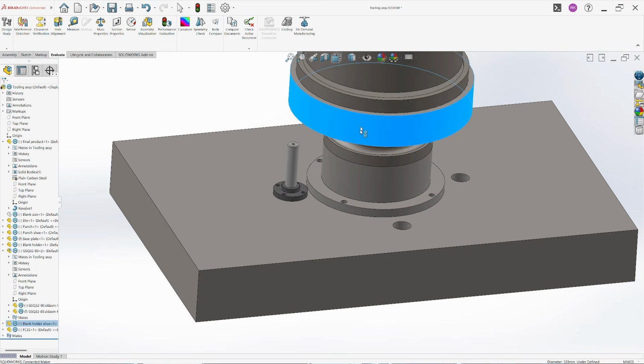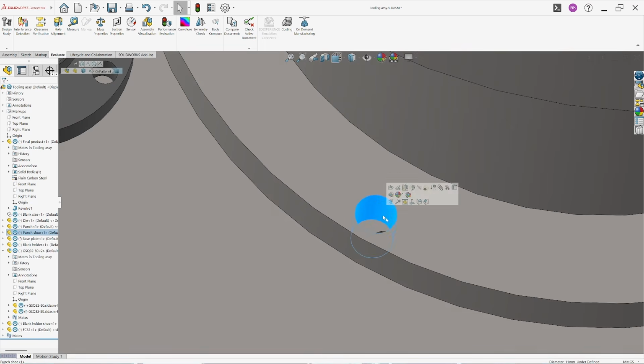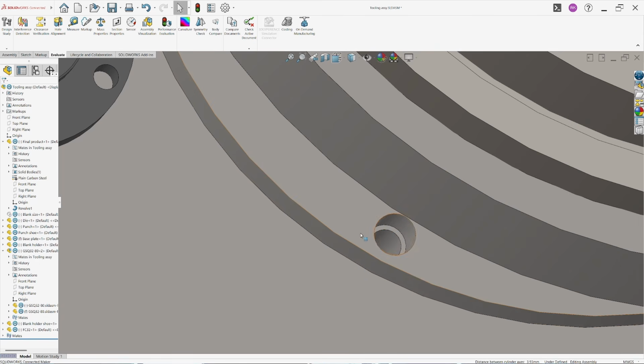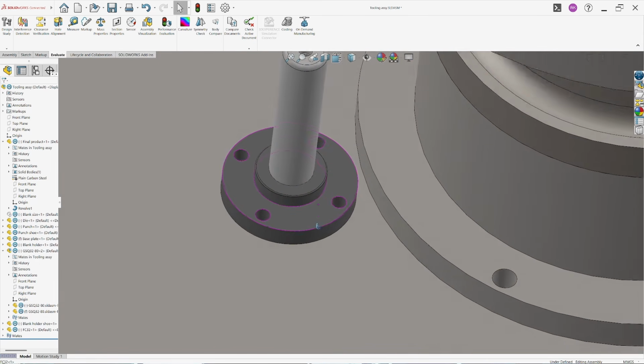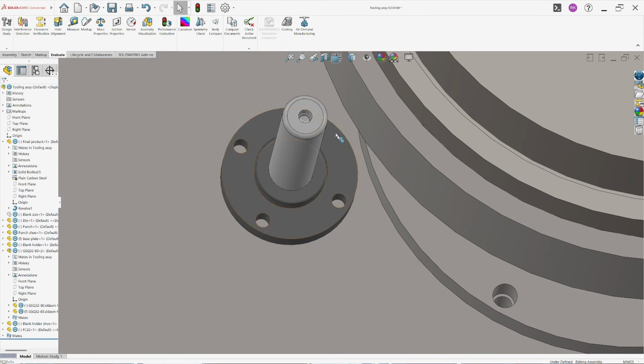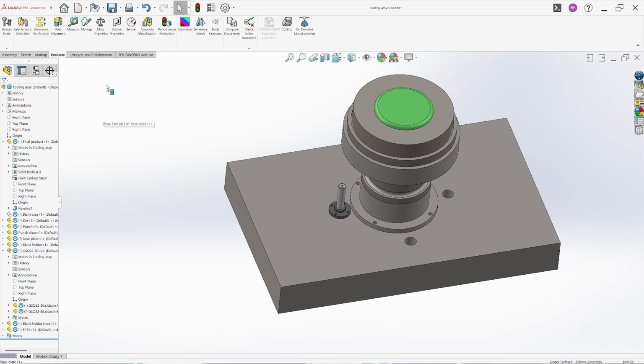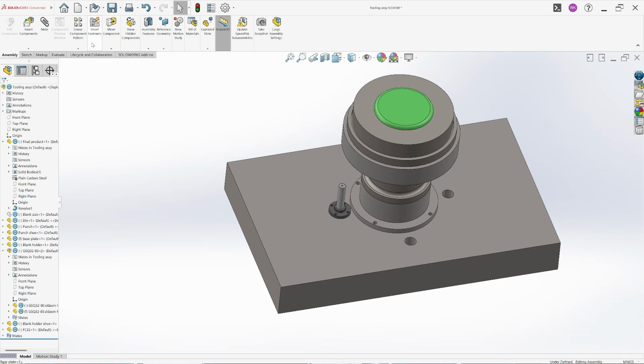Now we can mount this with the hole, something like this, right? Now we will also have to add the mounting holes for the gas spring, but I'm not going to do that. It's up to you. If you are following me along, then you can do it. Okay, here what I'm going to do is just pattern the gas spring and its mounting.